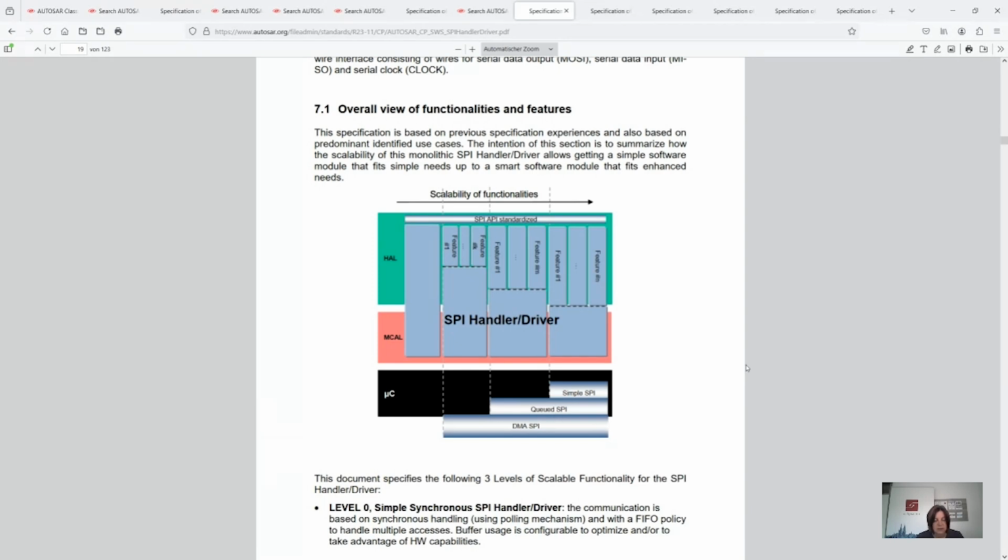So there were not enough pins. And then we had a lot of low side driver ASICs, for example, for the digital input and digital output. And then you communicate the status, how to change the pin via SPI. So this is one approach.